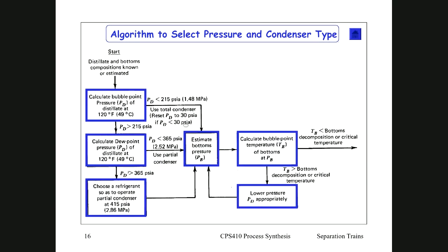Yeah, I always talk about 1 atmosphere, so that you don't use a pressure vessel. You don't want to have the possibility of air coming into your distillation column, because then you can have an explosion. So if you operate with a slight overpressure, you're fine.